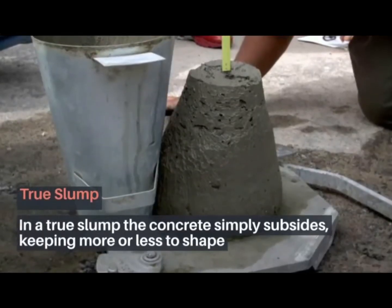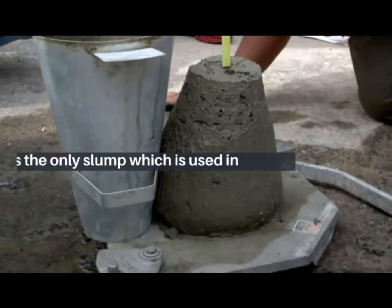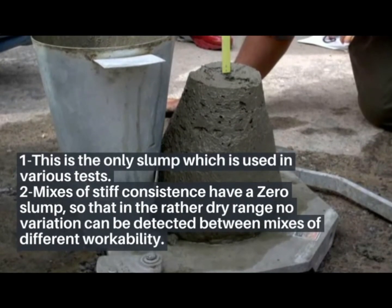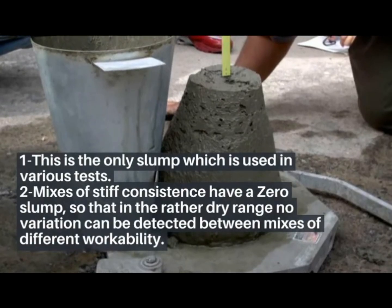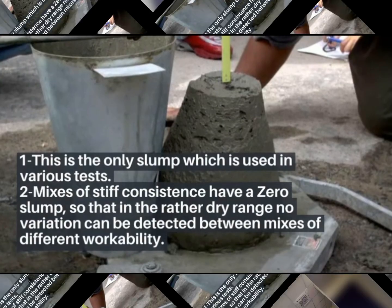True slump. In a true slump, the concrete simply subsides, keeping more or less to shape. This is the only slump which is used in various tests. Two mixes of stiff consistence have a zero slump, so that in the rather dry range no variation can be detected between mixes of different workability.